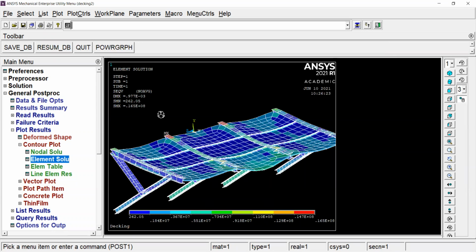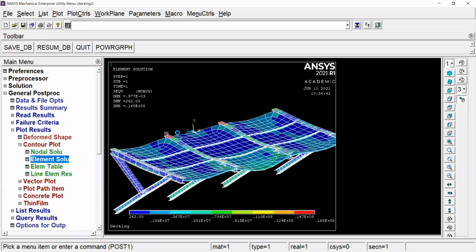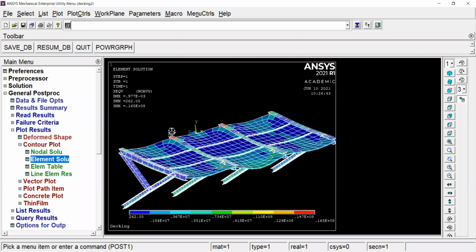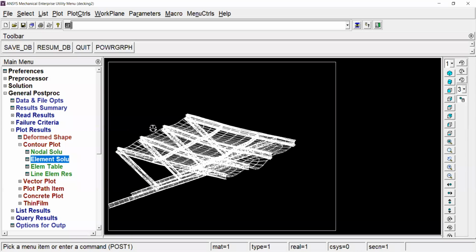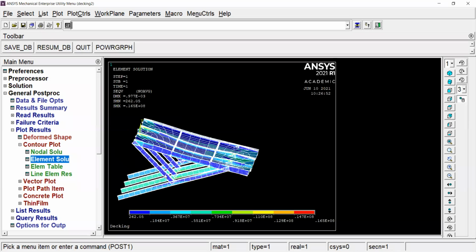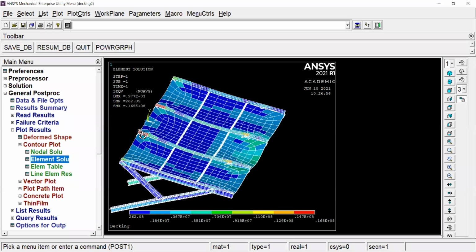We have stress hotspots, and it's telling us that the maximum stress that we're going to experience is 165 times 10 to the power of 6. Oh, sorry, this is actually 16.5 megapascals. That's the maximum stress that we're experiencing, which isn't that much. If you then compare this to the yield strength of the steel that we're using, you can also get that property from MatWeb. So this is mild steel. I think mild steel has a yield strength of 200 and something megapascals. And this is 16. So right now, this is more than safe.